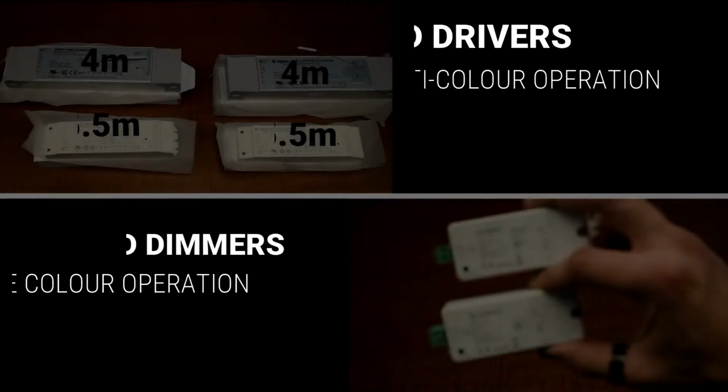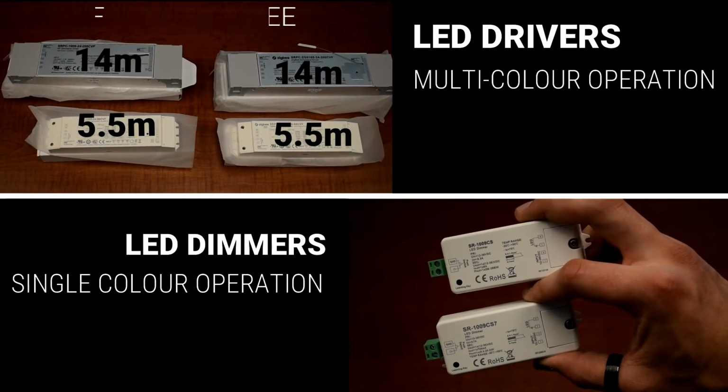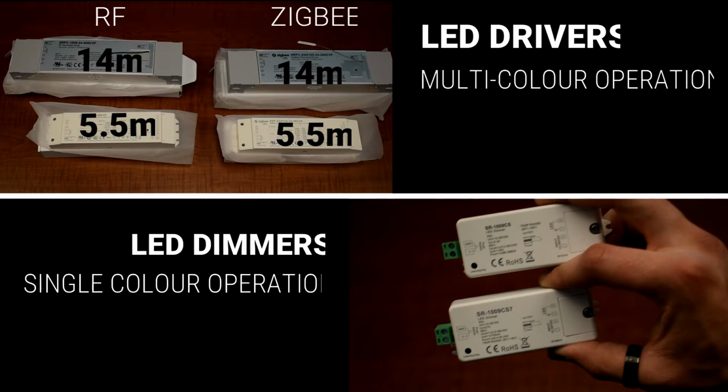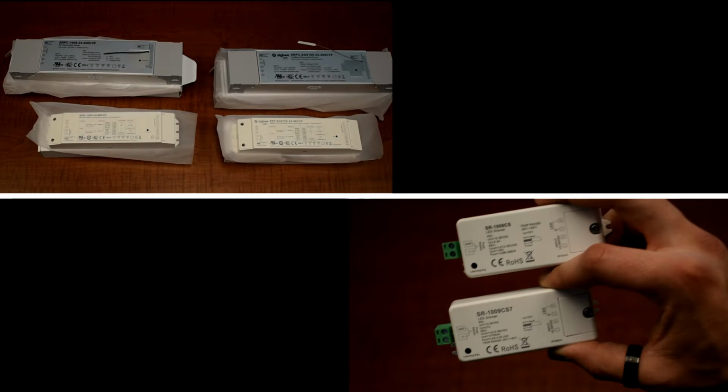In other words, if you're going with the halogen, LED white, or LED warm white, a single color dimmer will be sufficient. However, if going with an RGB option, you will need to use an LED driver. Noted in black is the recommended max length for the LED strip that the drivers can support.